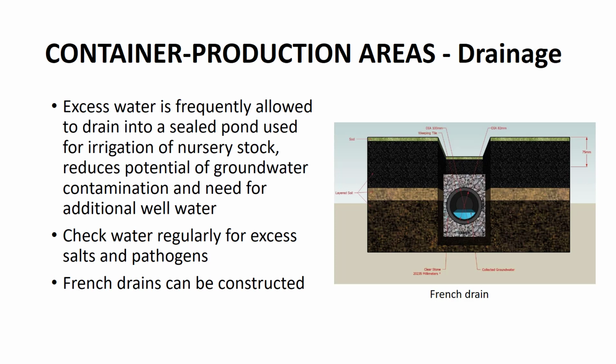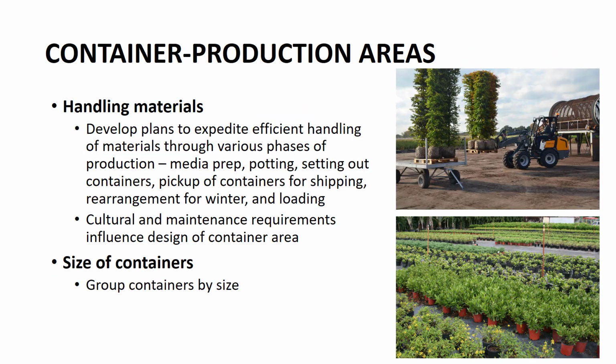Where the soil type permits, French drains can be constructed to carry away drainage water. French drains are simply deep holes or trenches dug through low porosity topsoils into high porosity subsoils. The trenches are then filled with rocks or crushed gravel. These drains allow the excess water to percolate into the soil where it will be filtered and will recharge the underground water supply.